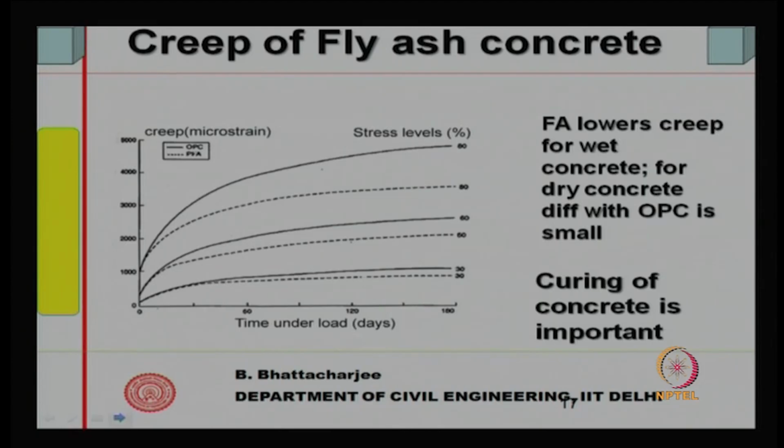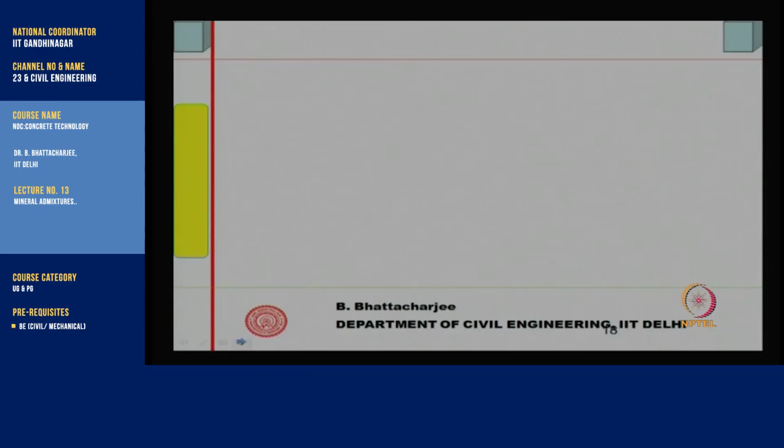Curing of concrete is definitely important, and you have to cure more in case of fly ash, because you want to ensure that the pozzolanic reaction really initiates and lime production always takes place. So, curing is very important, and curing is also related to creep and shrinkage.